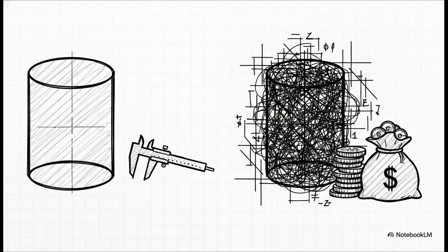So, what are the most common drafting mistakes we actually see out there? Looking at data from engineering forums and metrology experts, the biggest shop floor complaints happen when engineers just overcomplicate things. The absolute biggest sin is slapping a total runout callout on a part where a simple circular runout would have been totally fine, unnecessarily driving up manufacturing costs. Another huge one is anchoring the tolerance to an unstable datum feature or just failing to think about how the supplier will actually measure it. If your machine shop only has basic tools, a hyper-strict total runout callout might just get ignored or verified incorrectly anyway.